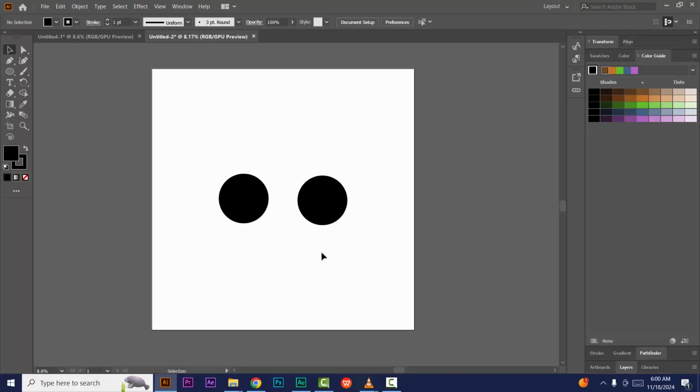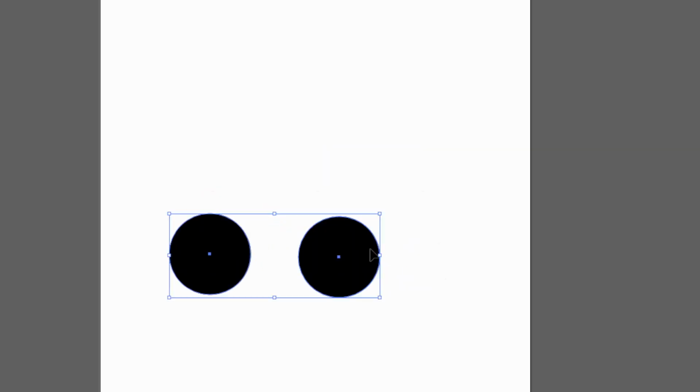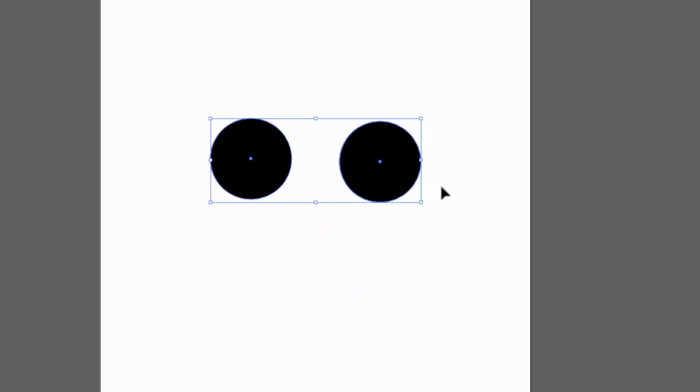The first tool is the selection tool, as we learned in our Photoshop for brand identity design. The selection tool allows you to select, move, resize and transform objects. Click on any object to select it. The selected object will show a bounding box and an anchor point around it. Hold Shift and click additional objects to select them together. Click and drag to draw a rectangle around objects to select them.